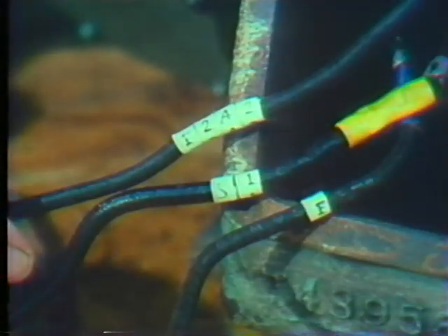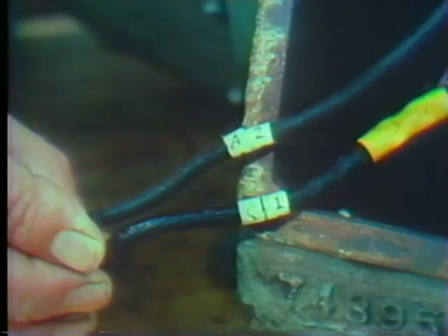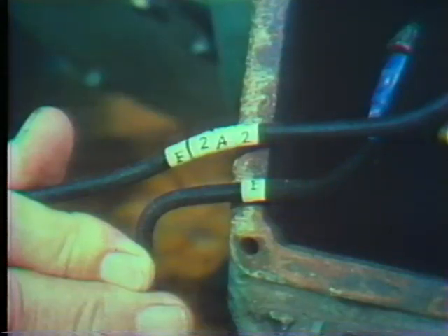If the nameplate's missing, then you've got to go by the motor lead markings. Remember, we said that the armature leads are marked A, the series field is marked S, and the shunt field is marked F. If your motor leads have all three markings on them, it's compound. If the leads are marked A and S, you've got a series. It's a shunt if the leads are marked A and F.